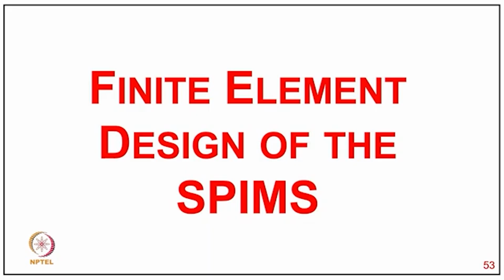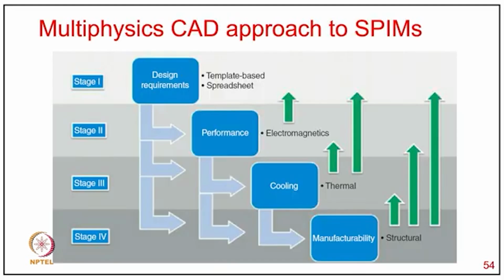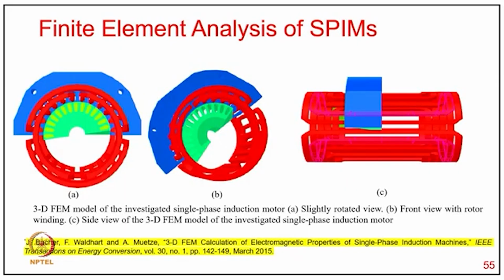Nowadays we are of course using finite element design for single phase induction motors, especially for very low ratings where these empirical relations do not work properly. Typically it is a multi-physics computer design approach for single phase induction motors, starting from stage 1, design requirement, then stage 2, performance, stage 3, cooling, and stage 4, manufacturability, and of course you consider a template spreadsheet